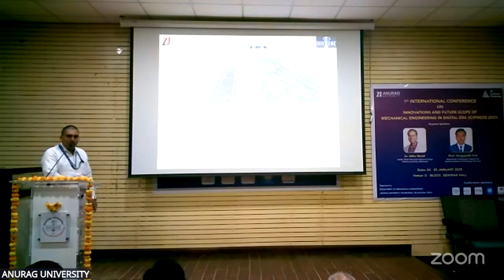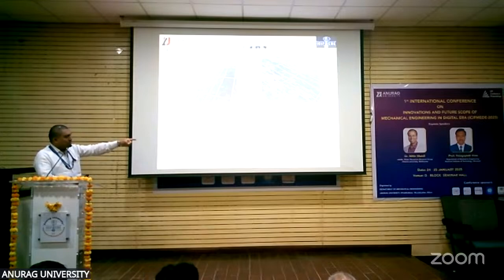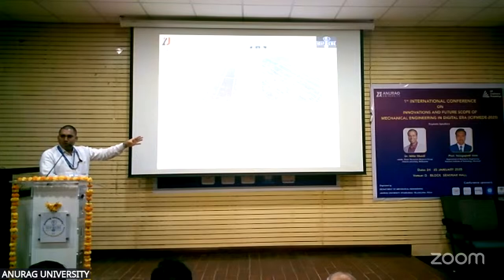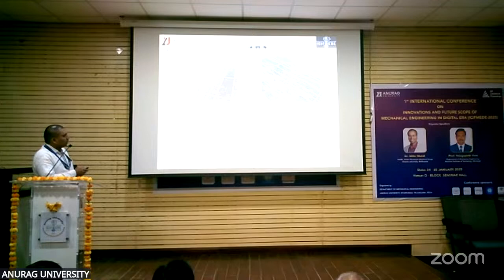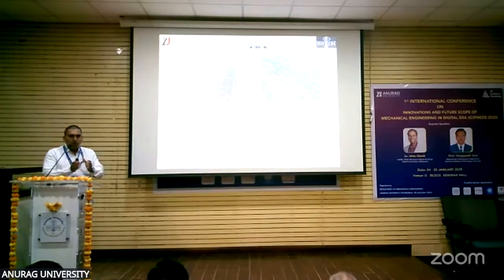This is the 15th day, showing how many bird droppings we got on the panel. On the 31st day, if you see, a huge amount of bird droppings were placed. That's why on the 31st day we got a 25.9% reduction in power. On the 15th day, we got an 18.7 percent reduction in power. For these 20 kilowatt panels we kept them clean. The remaining 20 panels we neglected, we didn't clean. So continuously birds were dropping droppings on those panels.